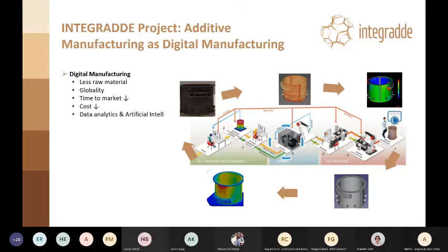This is a three-dimensional laser scanning of the component, and you can see here the deviations regarding the initial design of this component. You can see here that in the inner part the deviations are lower than in the external part. And for example, in this region of the component, there is a large deviation. I think it was about 1 millimeter.